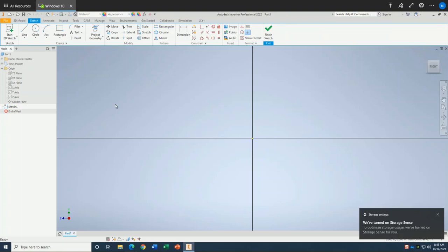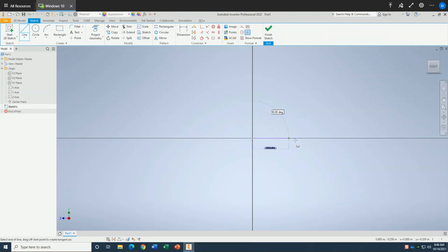So I'm going to go with the Line command, and I'm going to generate the lines from this point. I click on the line and select the start 0,0 point. The width of the house is going to be 3 inches, representing 30 feet.